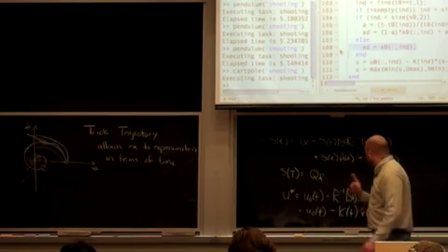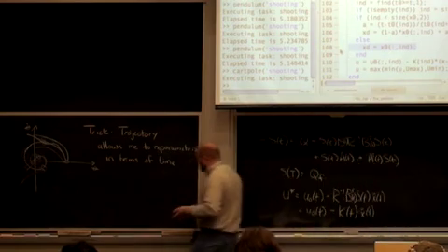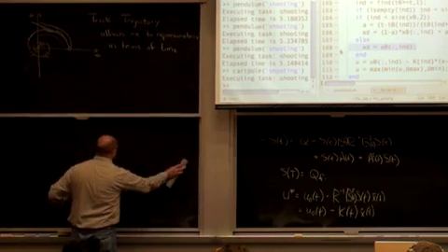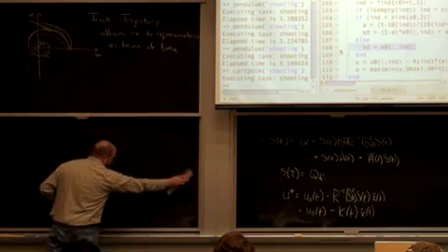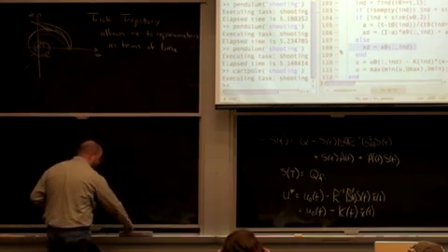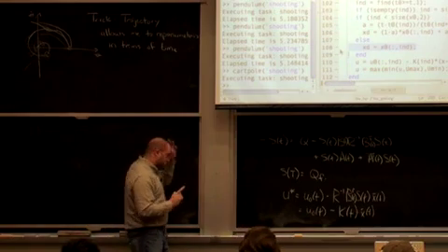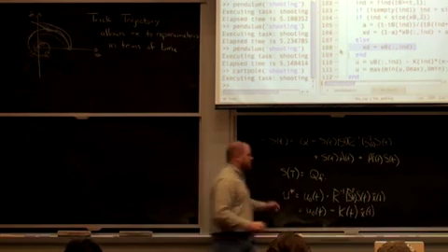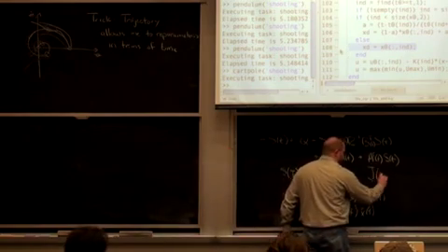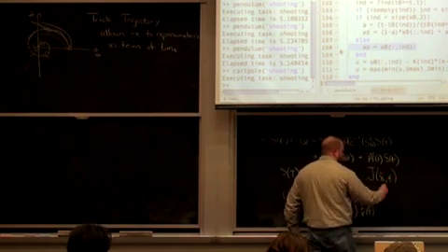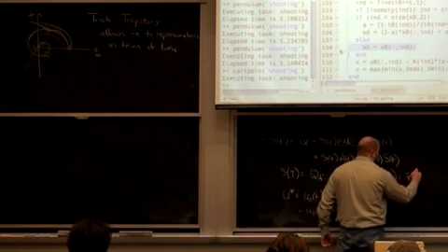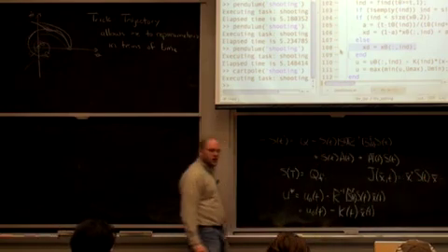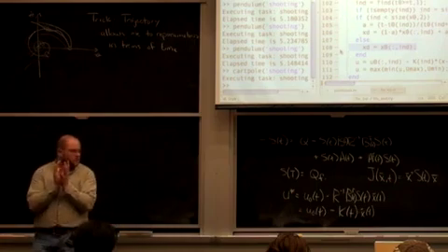Okay, I want to give you one more mental picture to think about what this is doing, so it sort of launches into the next thing here. So my cost-to-go function, which I just erased, is, remember, J(x̄, t) = x̄ᵀ S(t) x̄.